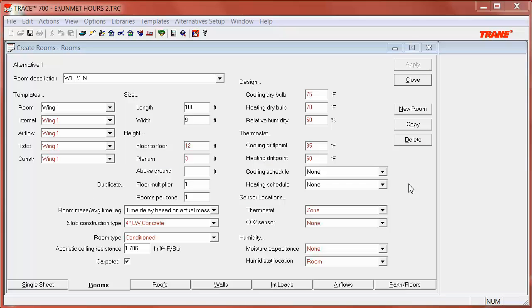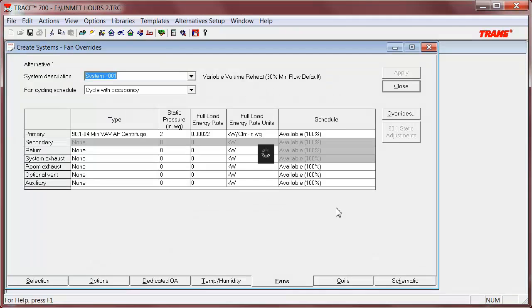When a space is unoccupied and there is no thermostat schedule applied, the space is allowed to use the drift temperatures. If there is a wide variance between the occupied set point and the drift point, the HVAC equipment may not be able to handle the pull-up or pull-down loads in the 1 hour time increment as the building becomes occupied, because the equipment is sized per the thermostat set points and assumes steady state conditions. Verify the temperatures entered are an accurate representation of the actual building thermostat controls. The same suggestion applies when utilizing thermostat schedules. However, realize thermostat schedules are not affected by occupancy, but rather follow the user-defined schedule exactly.